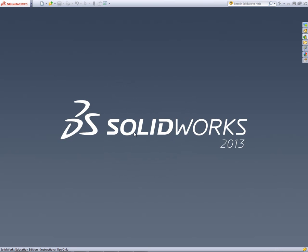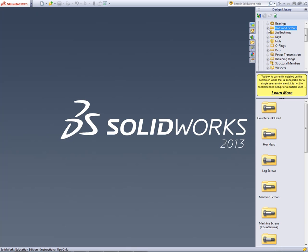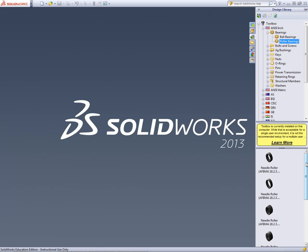We won't save anything. We'll go back to the design library again, left click. Now that we've loaded the toolbox, all the tools are listed up here above, and so we can collapse this little plus sign, and now we can move this down so that we have a better idea. But these are all of the things that appeared when we first started. Here's the bearings. We can left click on the little plus sign, left click on roller bearings, and down below it shows the types of roller bearings.